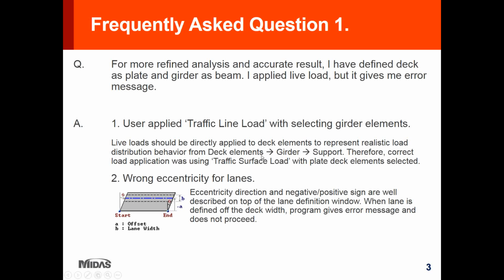and the description is described in the presentation. And for the second response, wrong eccentricity for lanes. I wouldn't say wrong, but it's too much eccentricity. When the lanes are defined outside of the deck width or deck elements, the program gives an error and would not proceed.